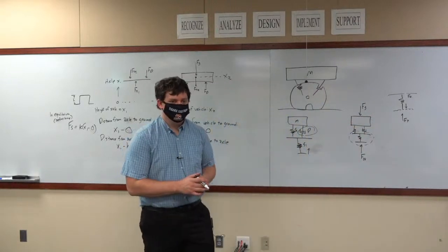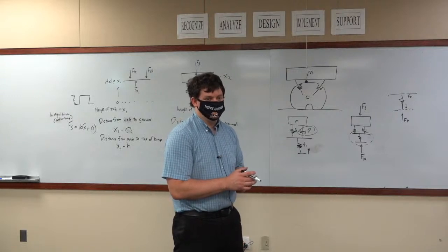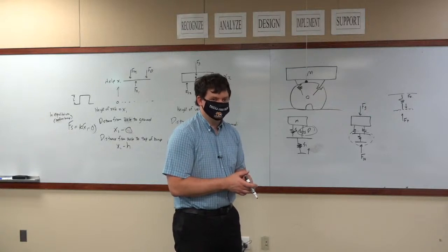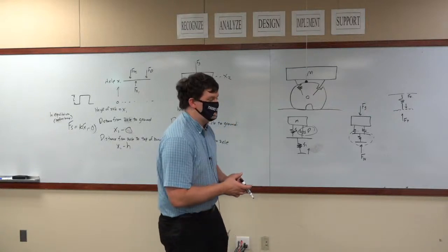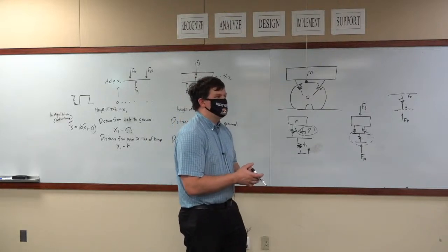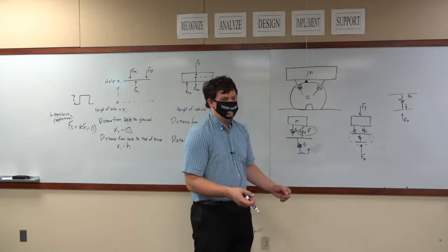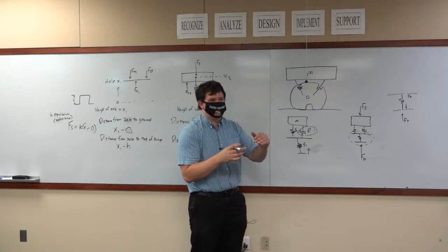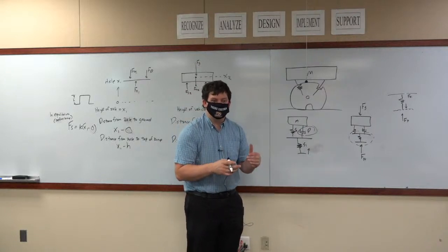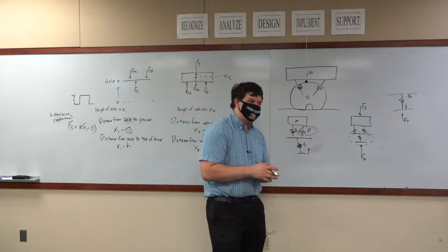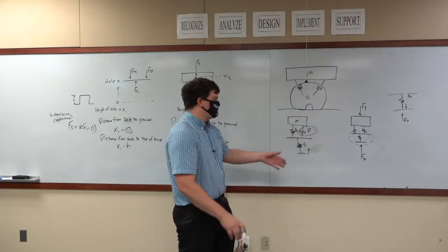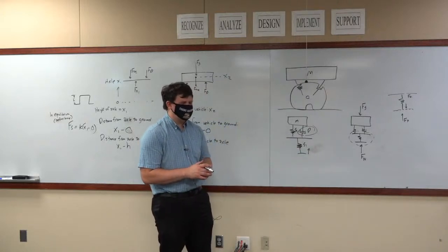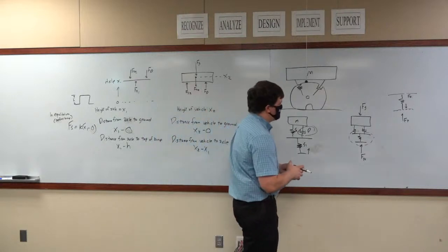Good point. Our equation become more complex if we consider once it travels a certain distance, then the mass would move. Yes. It would become more complex. Because what happens there is you have to exert a boundary force condition, where as soon as it goes upward a certain amount, then the force value that is transmitted increases exponentially. That does make the model harder. As long as you're dealing with low distances, that's fine. But that's why suspension is so challenging to model. That's why we're still designing it.